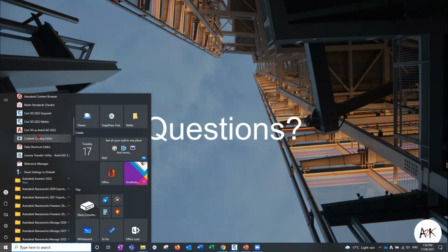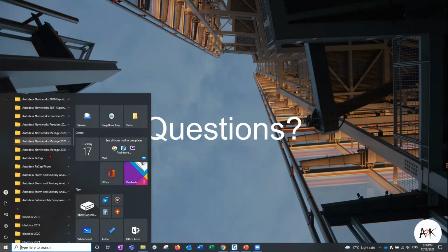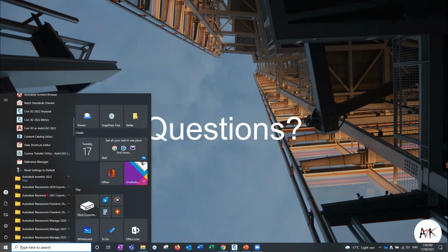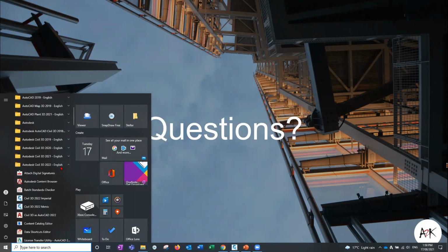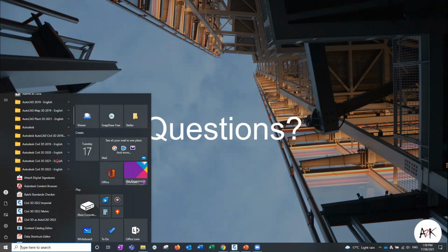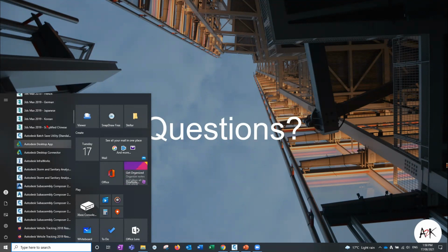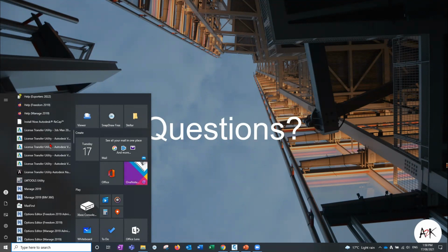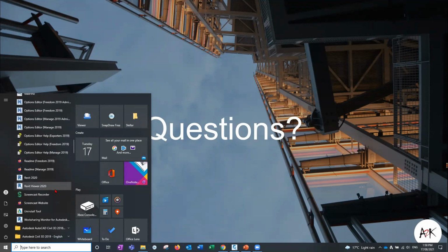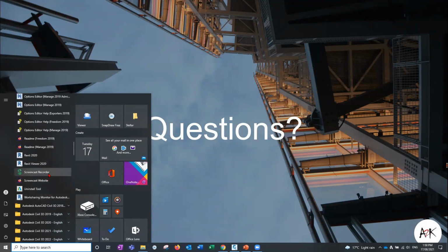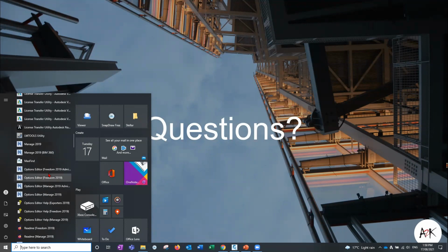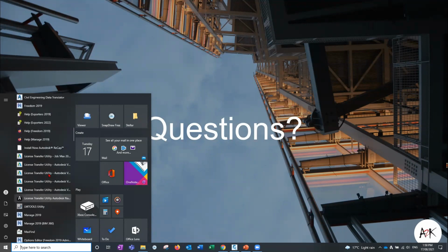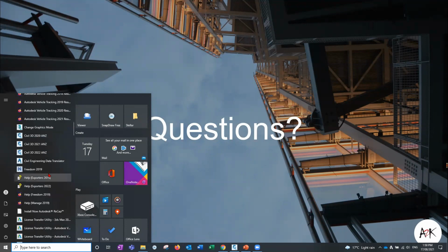Oh, maybe it's under Autodesk. It's either in here or it's a separate download. It's just a separate little program that you use to go and edit the catalog. No, I'm not seeing it there. It might not have got loaded with my 2022. But it's called the Pressure Products Catalog Editor. That's where you adjust the cut length.